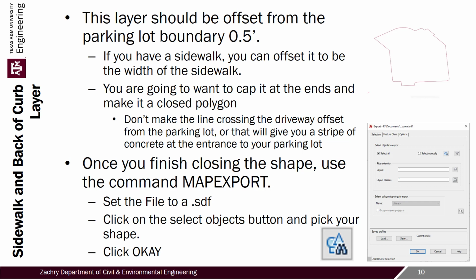So we can do it as a shapefile, which we messed around with before. And we can do it as an SDF file. That's the file I tend to like to use because it becomes a single file. If you remember, in shapefiles you have multiple files that reference each other, all with the same name. So you would have back of curb, and there would be a back of curb shapefile, a back of curb SHX file, a back of curb database file. This combines them all and makes it into one file. And so I tend to like this one a little bit better.